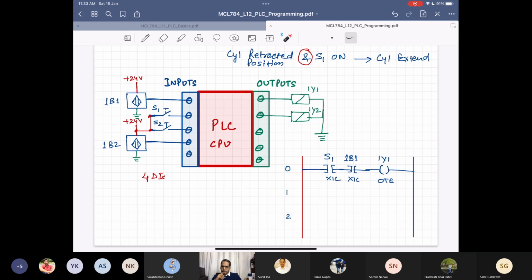That is also fine. Before you build the logic, you can just write down, and later on we'll see that we have to draw the table, and then normally we'll draw the table what condition is the prerequisite for executing that particular rung. So we will define the inputs here. So what is the input for the second rung? What should I be checking? So second functionality is that when S2 is pressed, your cylinder should retract.